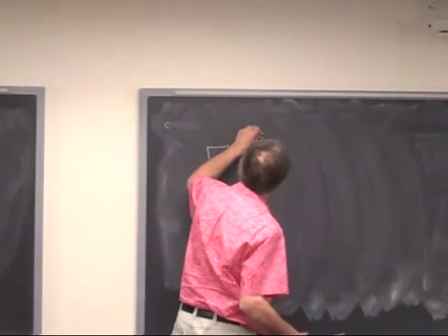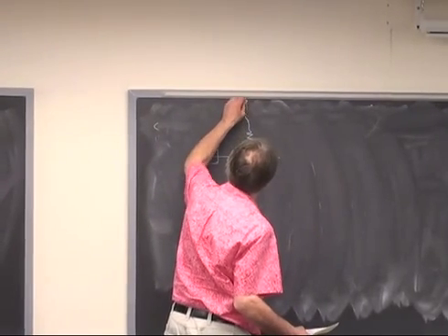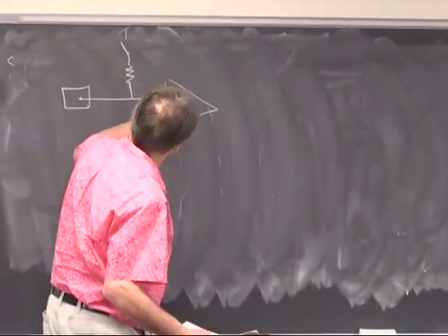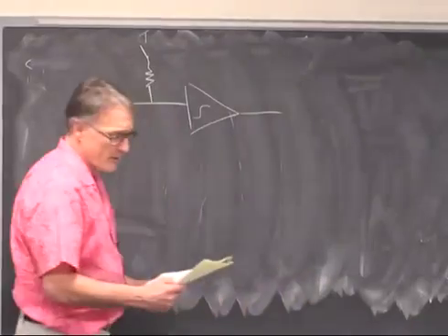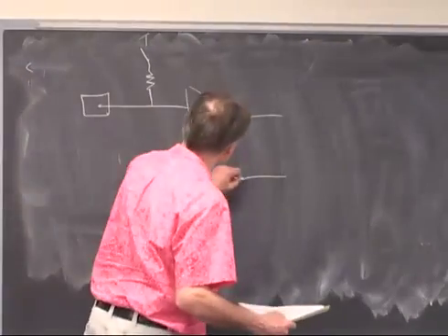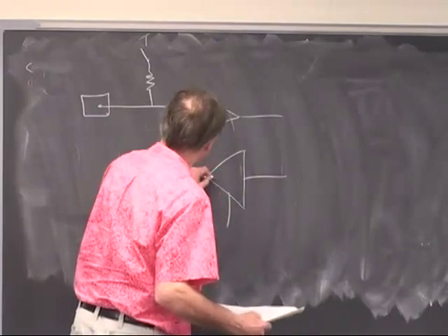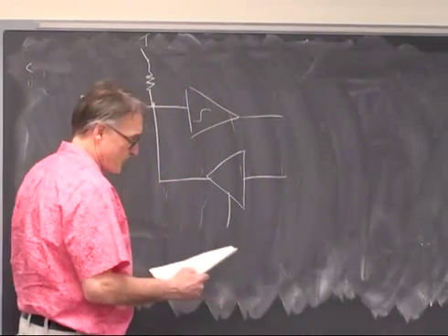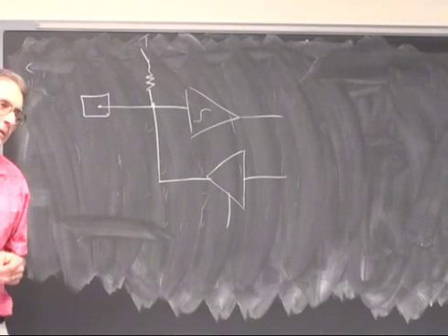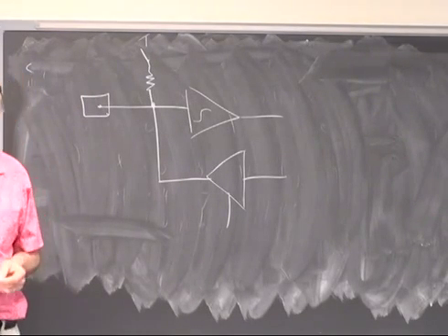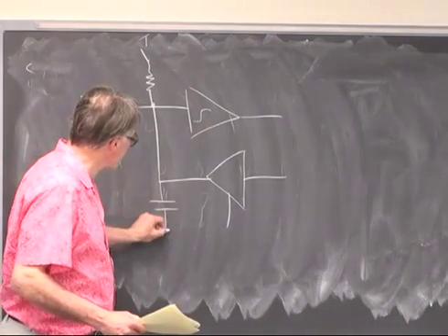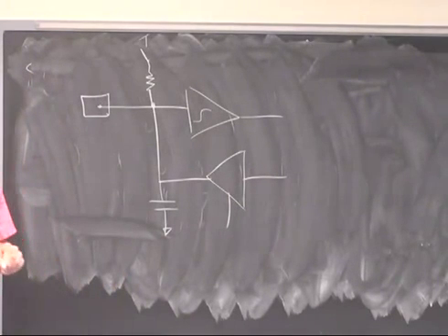There's the pull-up resistor, there's the pull-up resistor switch. There's a Schmitt trigger here, which is the input driver. There's a tri-state, which is the output driver. And then there's the piece you didn't actually build, but which is always there because wires are wires, and that is the parasitic capacitance of the port.